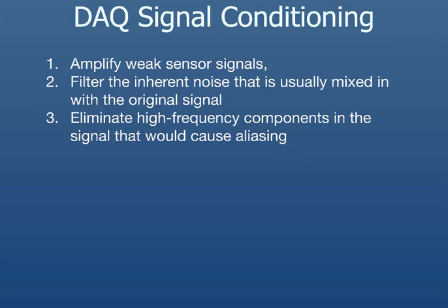Signal processing is also usually necessary to deal with induced noise that arises when signals are transmitted from sensors to other parts of the measuring system, even when efforts have been made to minimize the magnitude of this induced noise as much as possible. Analog signal processing is therefore essential to the processing of DAQ data, even if one is largely reliant on a digital computer-based system. With this in mind, we shall initially consider the essential aspects of analog signal processing with a view towards these techniques that are meant to address the three aforementioned concerns: amplification, filtering, and anti-aliasing.